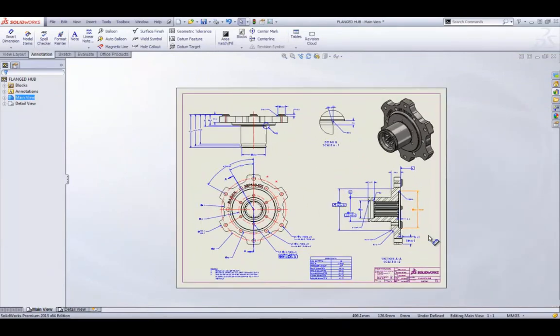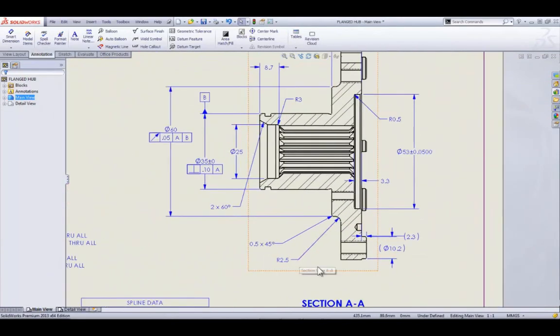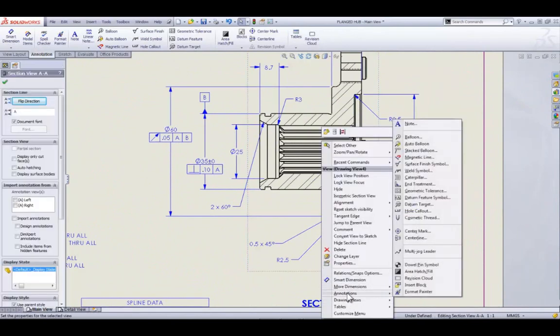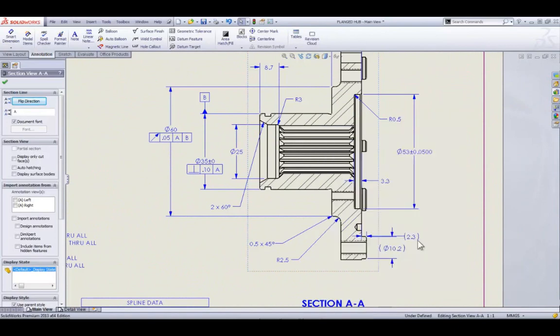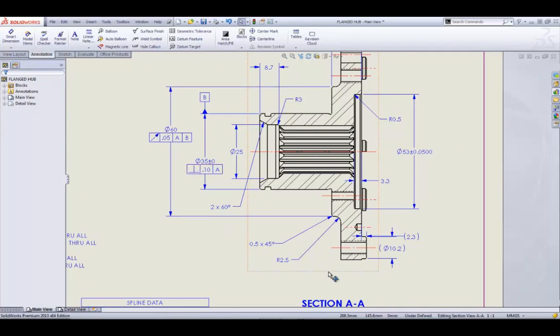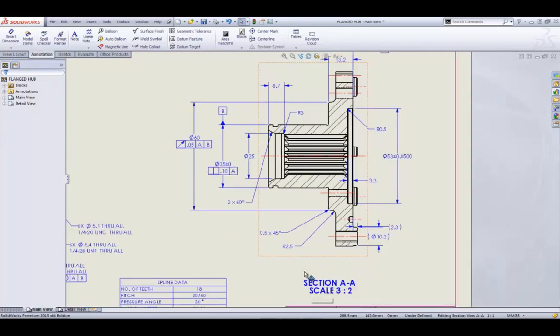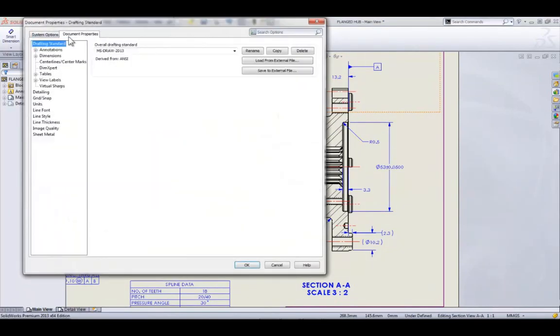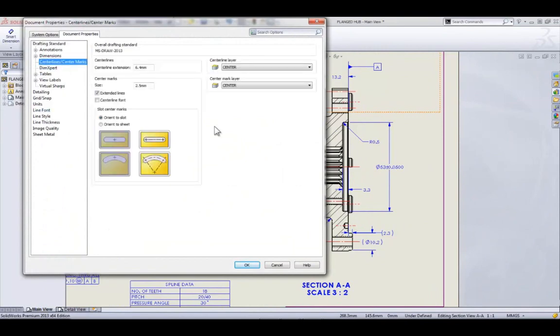All right. Other things, something that is not new, but if I go into this drawing view here and go into annotations, we can create center lines on the entire view straight out of the box. Now we have all these center lines. But what is new in 2013 is that if I go into my document properties and into my center line in here, center lines have now got their own place on layers.